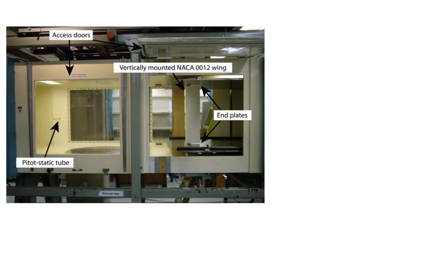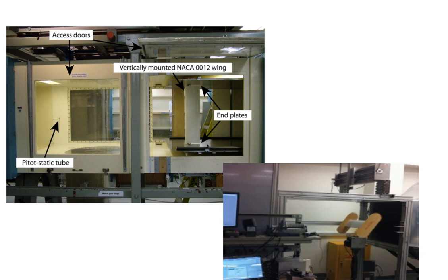the two-dimensional wing, this is again the laboratory studies which are performed by keeping the wing vertical and attached to the walls of the wind tunnel or the laboratory setup. Then again you can see here that the wings are attached to the walls by means of this wooden attachment. So the tips are not visible to the flow. The flow here is able to come and move over the aerofoil without even experiencing the presence of the tips.